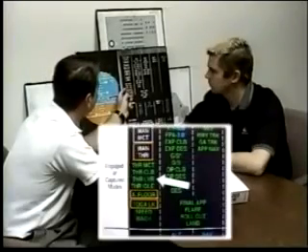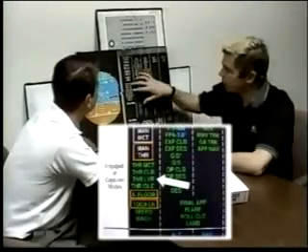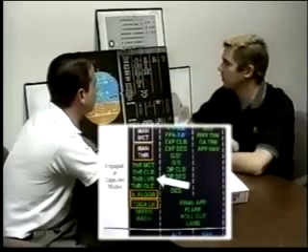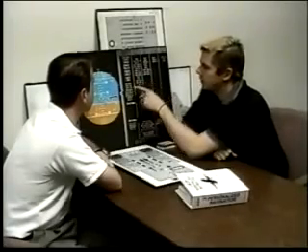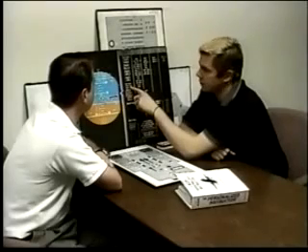And what about Thrust Lever? Thrust Lever kind of falls in between Thrust Climb and Thrust Idle. What's going on is Thrust Climb has been commanded, but instead of having the most forward throttle in the climb detent, the most forward throttle is after the climb detent, which is limiting the thrust that's available.